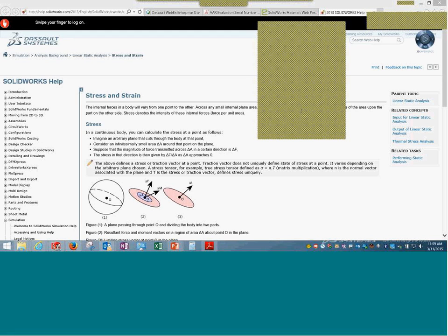If you try to understand the exact meaning of displacement, when you plot a displacement plot on software, what you're getting is the total displacement in the entire geometry. Am I right? It is not a localized displacement in a certain element or anything. It is more of a summation, and this is more a derived quantity than the local elemental thing.